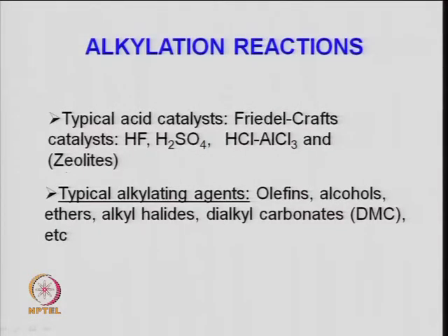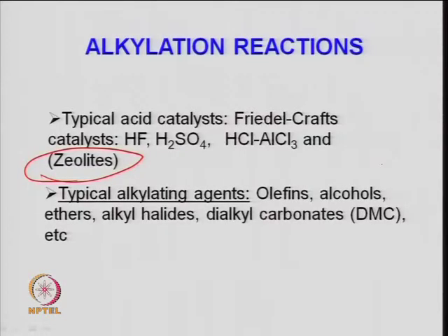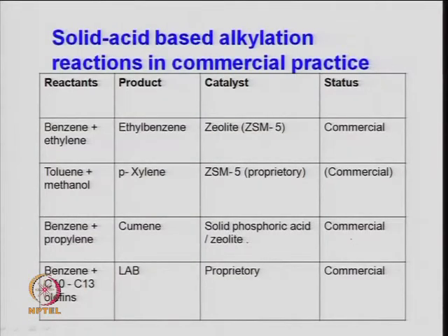The new trend is to use something like a solid catalyst. Although not well documented or very popularly commercialized, one needs to look at solid catalysts for the process, because they are easy to handle and material of construction is not an issue for them. These are the catalysts being used. Typically the alkylating agents and reactants are olefins, alcohols, ethers, alkyl halides, and dialkyl carbonates. As I said, it is a very important reaction in the industry.